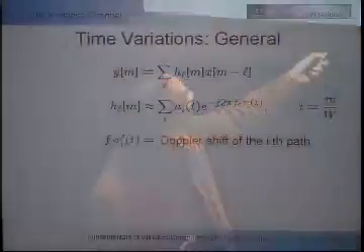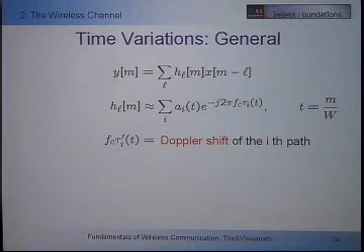If you want to forget about Doppler shift, that's fine, but you can see that the variation of this term will be a cause of the variation of the gains here. So the picture is, as my car moves away from the transmit antenna, the frequency is shifted, but that also means that the phase is changing linearly.